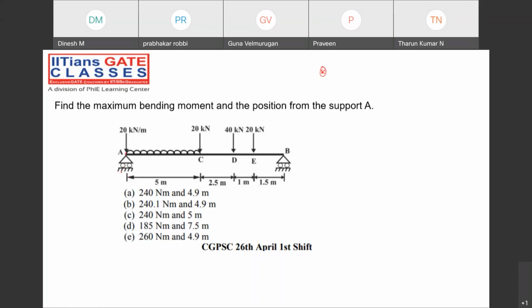Of course, here one correction you can make. There cannot be two roller supports. There must be one hinge support. So reaction forces will be coming in this direction, and this direction. By making the summation of force y to be 0 and summation of moment about A to be 0, you can calculate RAV to be, let me directly write, 98 kilonewton. Check it out, any one of you. And RB will be 82 kilonewton. Please check it out. Are you getting these answers? Reaction forces?